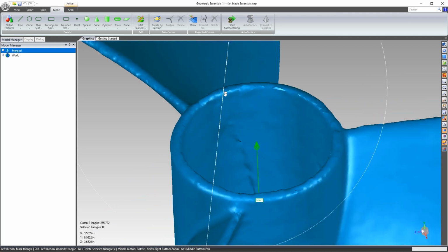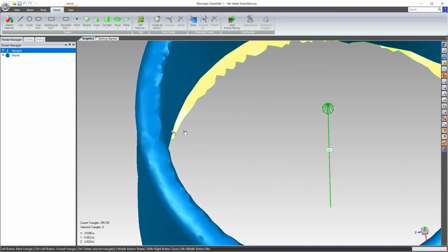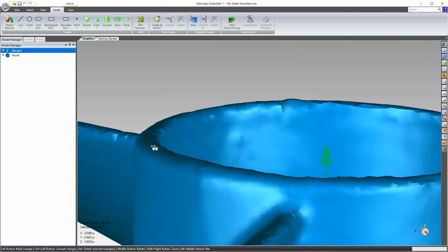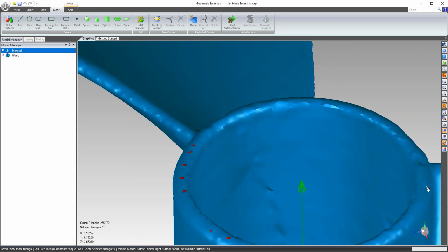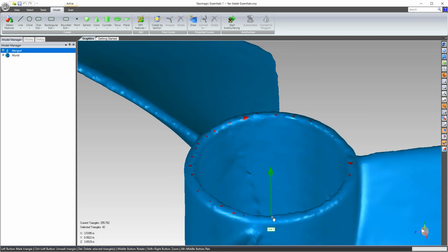Now the next step is to put a plane on top. The top surface isn't as well defined because it's a pretty sharp, small little landing area. So I'll grab that lasso selection tool and click some areas on that top surface, because there's so much curvature there that there's not enough for that other method to work. This will give me enough averaging all the way around the outside that I can get a pretty good plane. Also, when I do the alignment, I'm going to use that central axis as my main axis anyway, so that's going to be the primary axis of alignment.